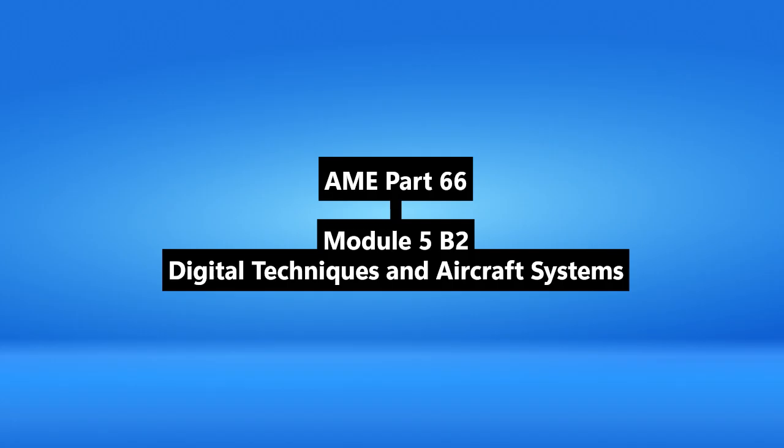The module brings up DO-178. What is that exactly? DO-178 is the standard for software safety in aviation, recognized globally by FAA, EASA, everyone. It establishes different design assurance levels, DALs, from A down to E, based on how bad the consequences would be if the software failed. Level A is for software where failure could be catastrophic, think primary flight controls, core navigation. Level E is for software where failure has no safety impact, maybe like some cabin entertainment functions. And the higher the level, the stricter the process. Massively stricter. Level A requires the absolute highest degree of rigor in development, testing, verification, documentation, proving its safety integrity.